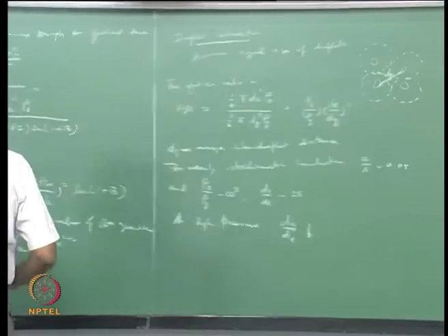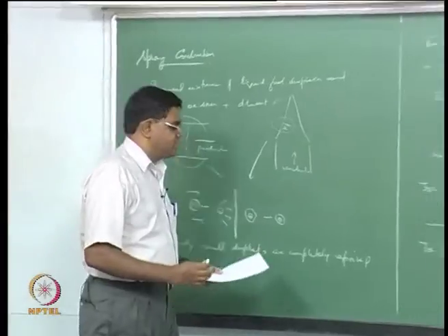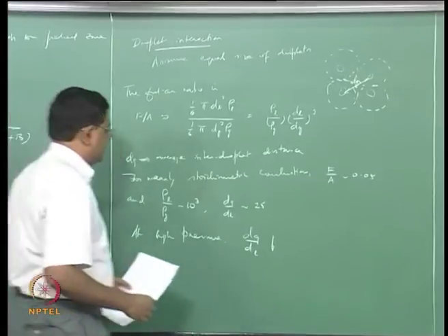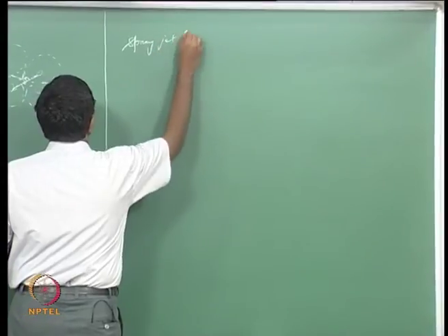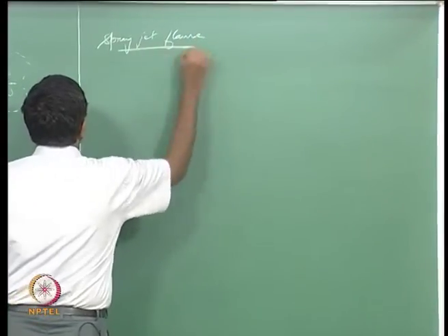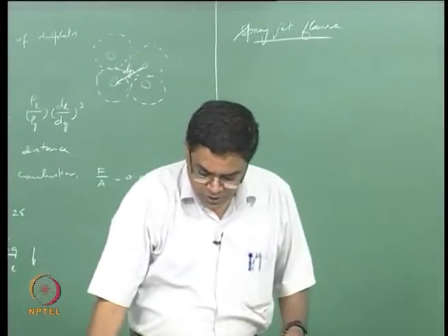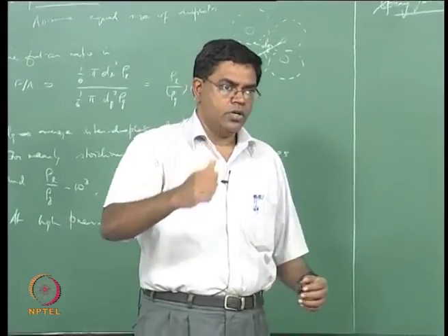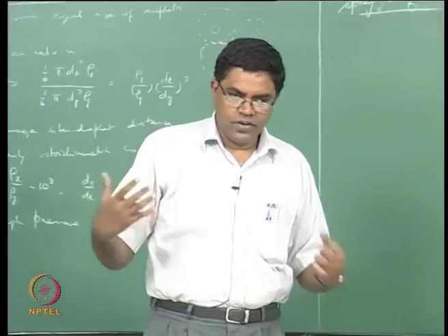What we should then start to think about is, we started looking at a premix mixture, but let's now look at a spray jet and a spray jet flame. This is now getting closer to reality. So what's going on here is two things. One, as you now have a jet that is coming out, this is jet of liquid fuel, it's also beginning to entrain air, and then of course we have ignited it, and there is a flame.